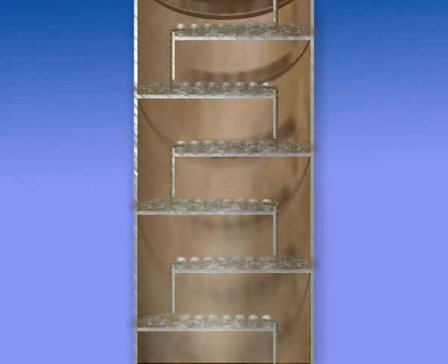When liquid levels get too low, an undesired passage to the downcomer area can result. Vapors will find the way of least resistance and will move up through the downcomer area instead of through the bubble caps. No interaction between the liquid and the vapors will be established, and the distillation process will be seriously compromised.